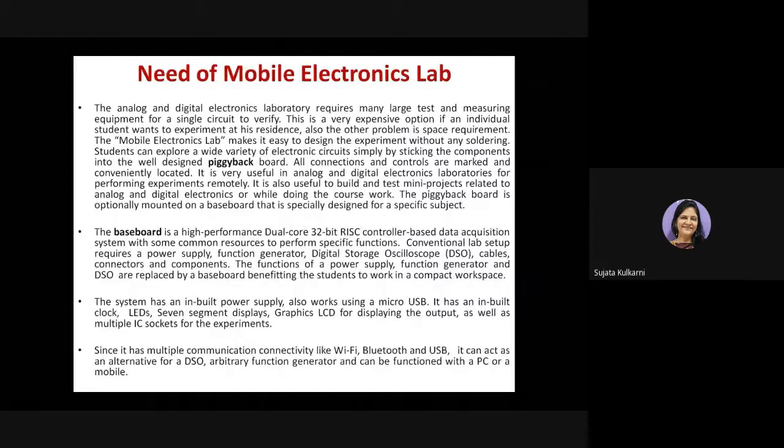So this entire system is divided into two parts. One is called the baseboard, the other is called the Piggy Backboard. The Piggy Back is an optional one which is mounted on the baseboard. The Piggy Backboard is designed as per the subject. The baseboard is a commonality for all the subjects. The baseboard is a high performance dual core RISC-based system or a data acquisition system. And the conventional lab setup requires a power supply, function generator, DSO, I told you already, cables, connectors, and components. So naturally, these things are a part of the system.